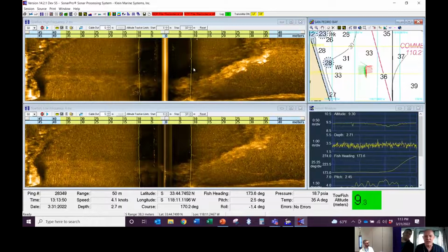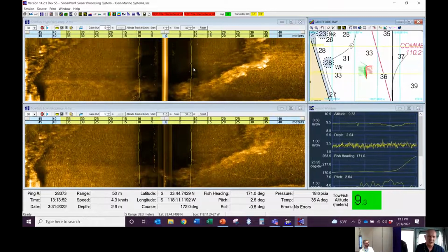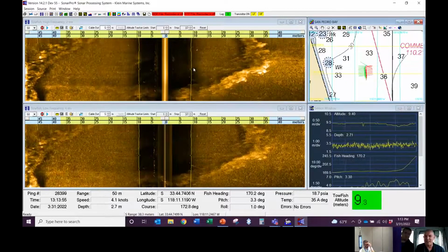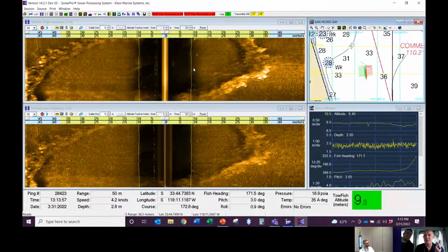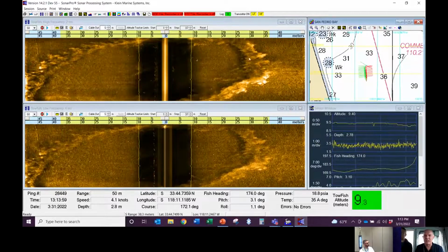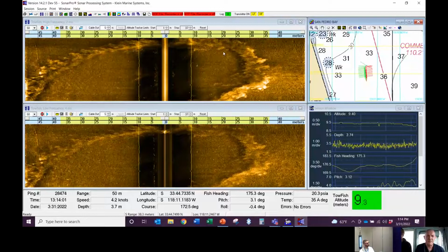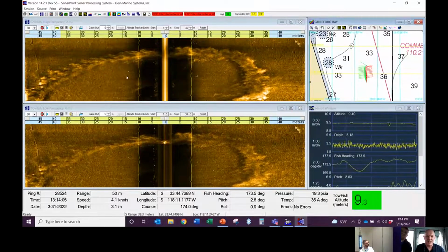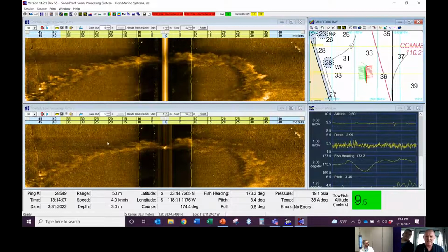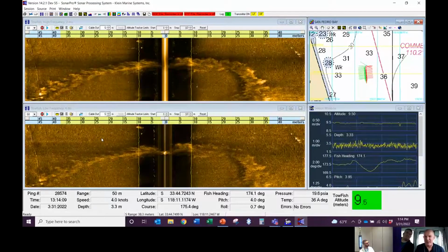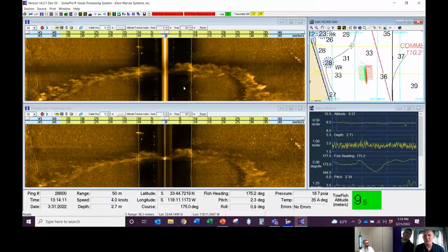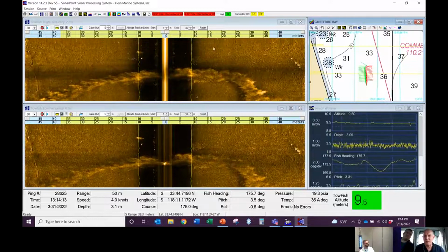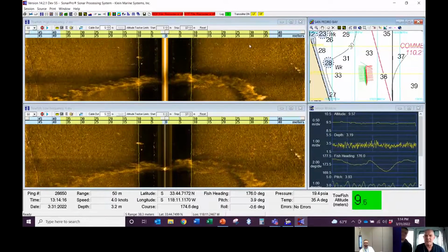This is due to the 360 kilohertz single beam echo sounder that we have in the tail of the Towfish. As we've straightened up, we're still seeing a little bit of our boat wake on this side. This top screen is the 600 kilohertz data, and the bottom screen is the 300 kilohertz data. Now that we've got rid of our boat wake, we can see that we've got rock solid data all the way to the edge there.